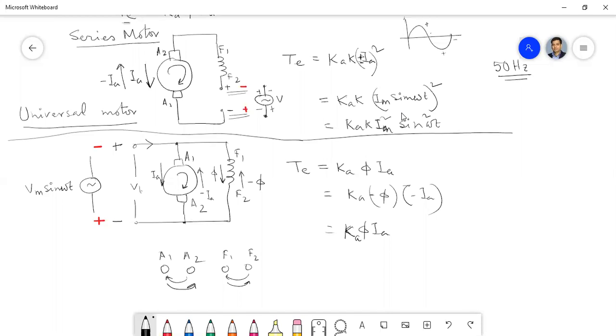So the torque produced by the positive and negative cycle will cancel out each other. So it won't rotate. Torque? So the torque produced during the positive and negative cycle will cancel each other out. So it won't rotate. Why do they cancel each other? Because again, alternating supply means nothing but a supply polarity reversal, isn't it?